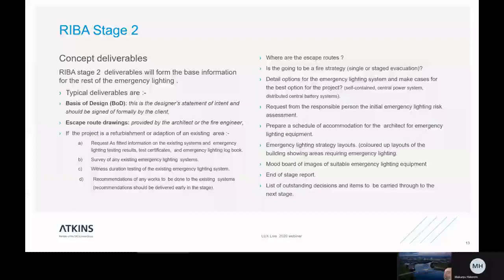Request the responsible person for the initial emergency lighting risk assessment. That is absolutely key, because when you start to do this, you will then start to be able to address additional emergency lighting requirements, which are project specific beyond the table that is in for high risk lighting in the areas there. An emergency lighting and risk assessment may actually say that you don't need emergency lighting in certain areas there, and you could use borrowed light from daylight because the building is only occupied during the day there.